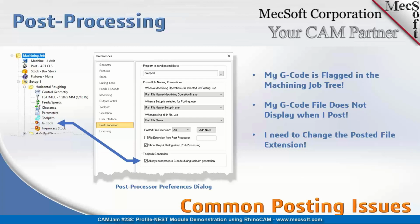Another thing that users ask about is why isn't their G code displaying? Typically, when you right click on operation and post, your G code will pop up automatically. By default, it'll pop up in a Notepad text file. So the Notepad will pop up, and you see on the top of this dialog, it says program to send posted files to. By default, it's set to Notepad.